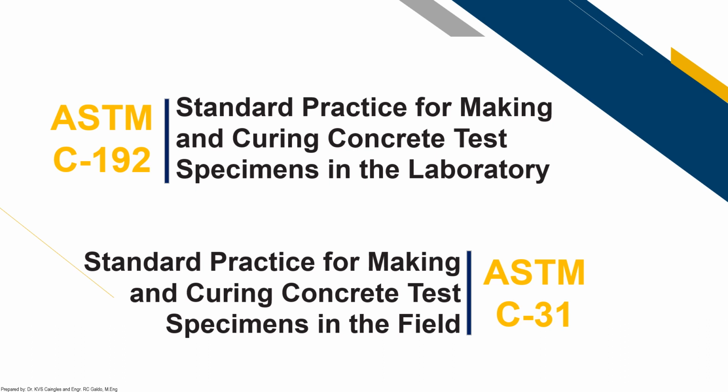Okay, and then per procedure, it is denoted by a code. For the case of standard practice for making and curing concrete test specimens in the laboratory, the code is C192, and if in the field, the code is C31. Okay, so both provisions under ASTM will be discussed here.